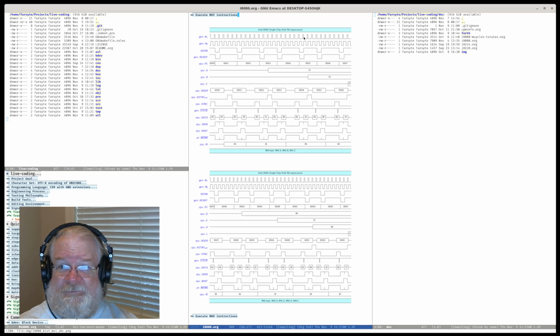And we can draw single bit signals like phi1 and phi2 and ready and so on. We can draw buses like the CPU, the PC, and so on. And these can have a line down the middle saying either it's high impedance or we don't know what it is. Coming out of reset, we don't know what some things are. The contents of A is arbitrary until this particular time when it's got to have a 1-1, and so on. I think that I set up something so that you could even have a grayed out cross-hatched area to say that it's in transition or undefined or please don't sample this.